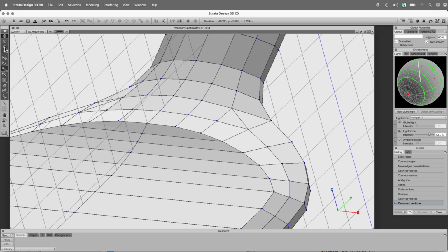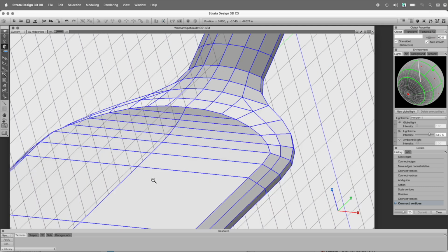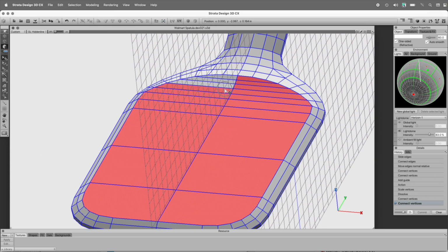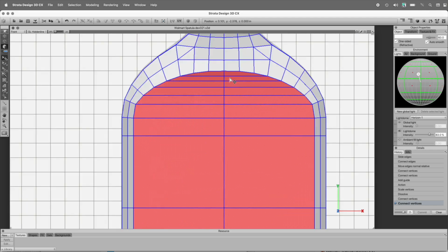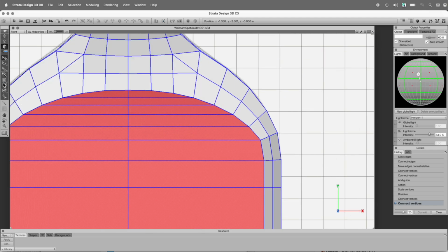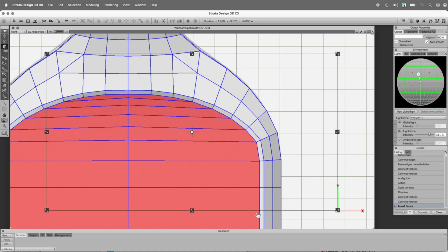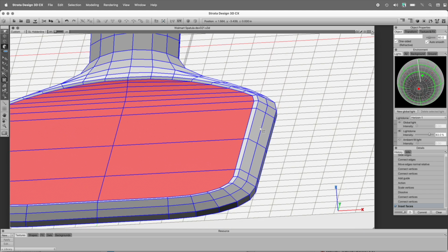So now let's return in face mode with the move tool to this area in here. I'm going to hold the shift key and just select all of these polygons and then come over to the extrude inset tool, click, hold, and drag, and just pull in this perimeter boundary, which will produce a constraint on the subdivision here, and it'll give us just a little bit of rounding.